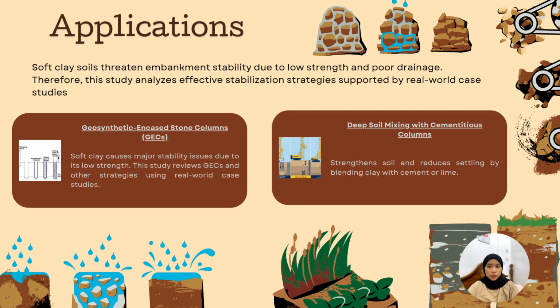So the first strategy that we look at involves geosynthetic encased columns, or GECs. When soft clay lacks the strength to support heavy structures, GECs provide a reinforced foundation. The geosynthetic casing keeps the stone column intact, giving the soil excellent load bearing capacity while also improving drainage.